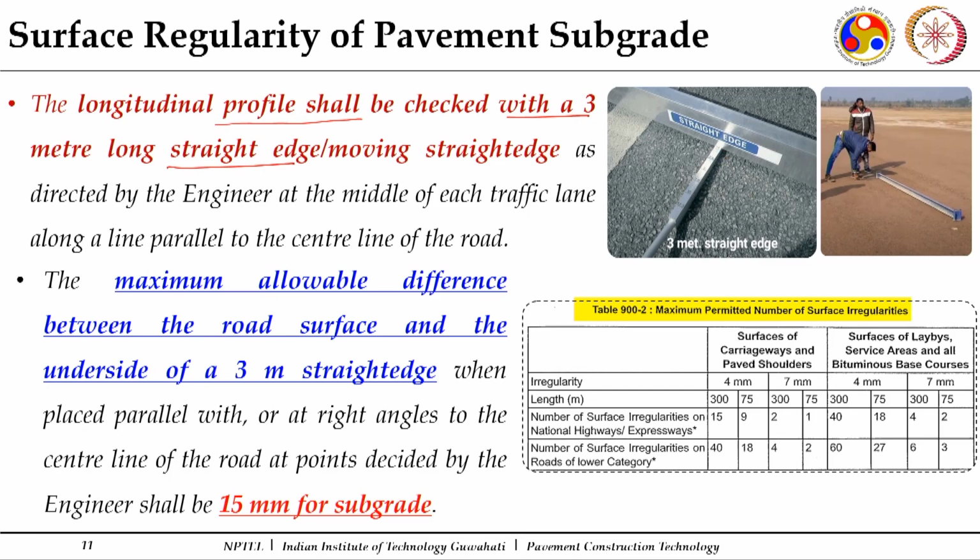If a surface is perfectly straight, there will be no undulations under it. So, this wedge when inserted will show how much undulation there is. If the gap is, say, 4 centimeter, whatever is more or less than 4 centimeter will show the amount of undulations.